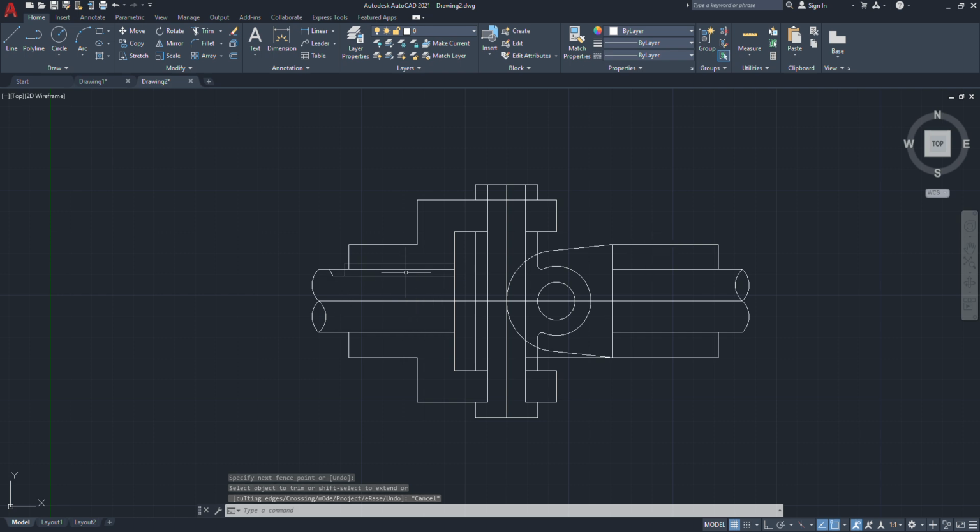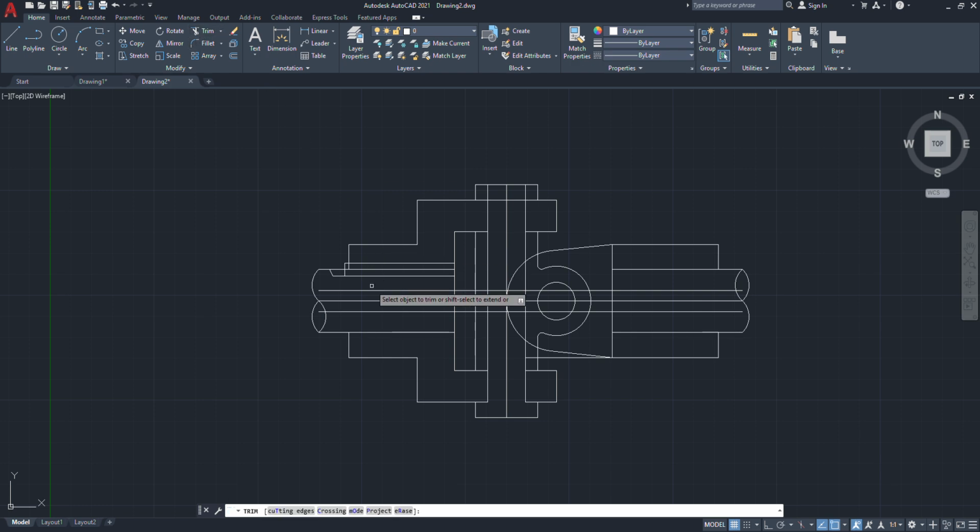So that is one side key, and here also we have to make one more key. There the width is slightly larger, we'll take a 12 mm width key, so 6 mm offset on either side, or a 5 mm key, so it is 5 mm on either side. This line like this, and we'll trim all these portions.